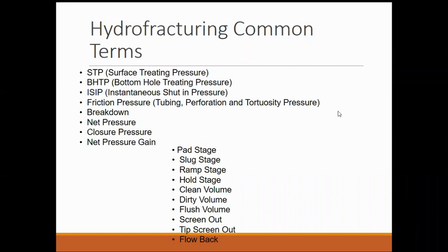Friction pressure: you understand that there is pipe friction. Your fluid will be pumped through different tubulars of different diameters and different make, so it will impart friction on your pumps. That would be an additional pressure. Then breakdown pressure: the pressure at which your formation or reservoir rock breaks down and initiates a fracture.